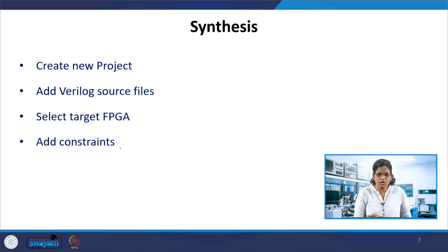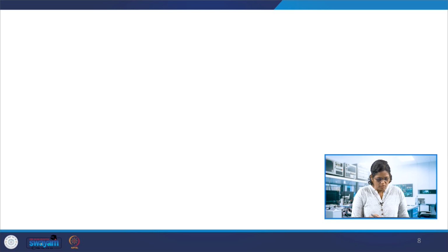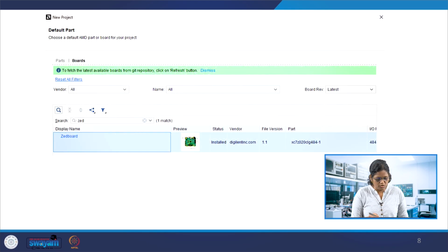The pins that communicate the inputs and outputs, those details will be given in the constraint file. The constraint file also carries the information of which pin is dedicated to the clock, apart from the input IOs. These are to be added in the synthesis process. If it is only synthesis just to see the schematic view, it may not be required to have the constraint, but if you want to see the outputs and dump the code, then the constraint is mandatory.